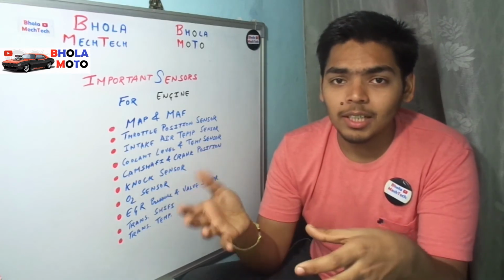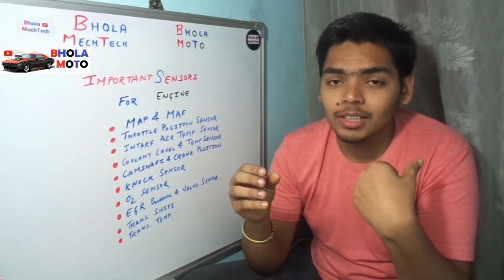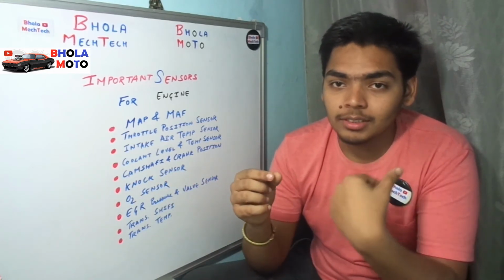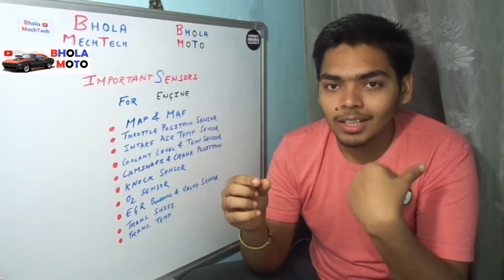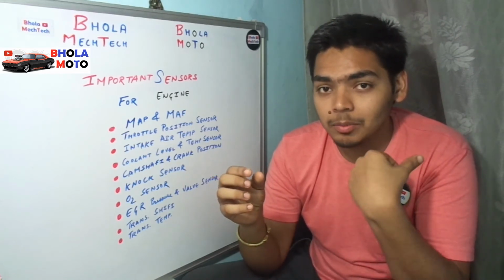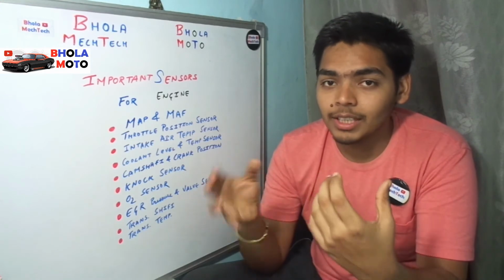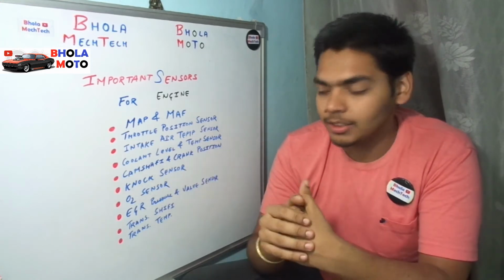Knock sensor is basically a piezoelectric sensor which senses whenever there is some pressure applied on that sensor, and when this piezoelectric crystal experiences some pressure, it generates a voltage, and then this voltage is sensed by the ECU.